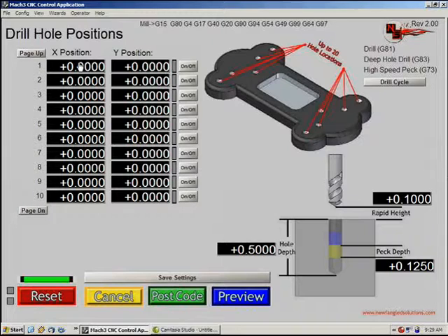So if I was actually to program in positions for a hole pattern, here I would turn on the position and I could move back and forth through the wizard set to actually type in all my data, turn all of the hole pattern stuff on, set my drill cycle to a G81, put a small depth, post the code, come back in, turn off the holes that were the wrong size hole for the drilling operation we're going to do, change my cycle, change the depth, post the code, and go back through.